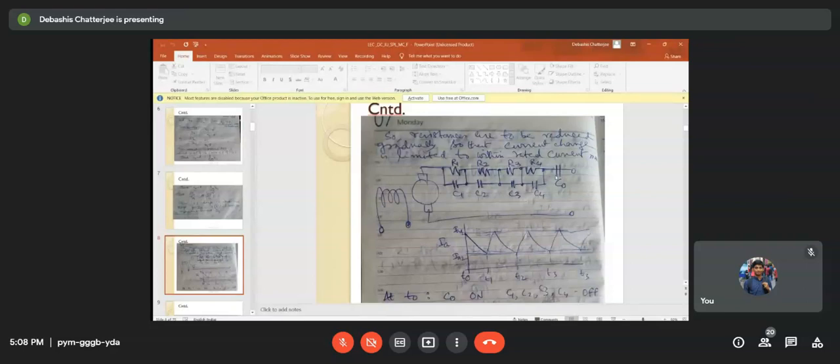So initially the main contactor C0 will be on, right? So that your current flows through all the resistances R1, R2, R3, R4, and the total sum of these 4 resistances will give you the R external value, which I was showing earlier. Now, after some time, when the current has reached IA2, C1 is switched on.